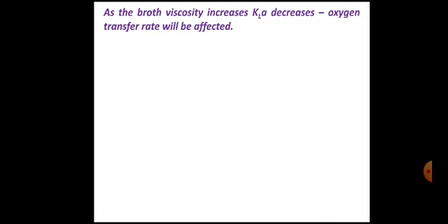So as the viscosity of broth increases, KLA decreases, the aeration capacity of the fermenter decreases, and the oxygen transfer rate will be affected.